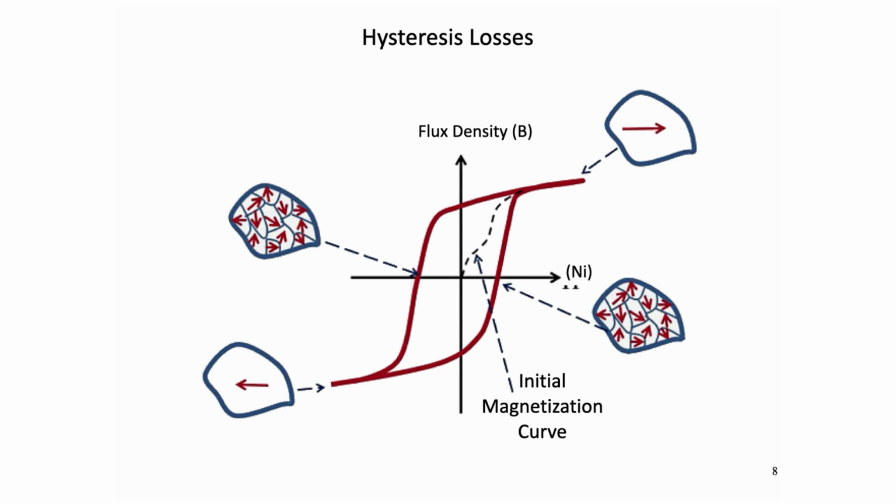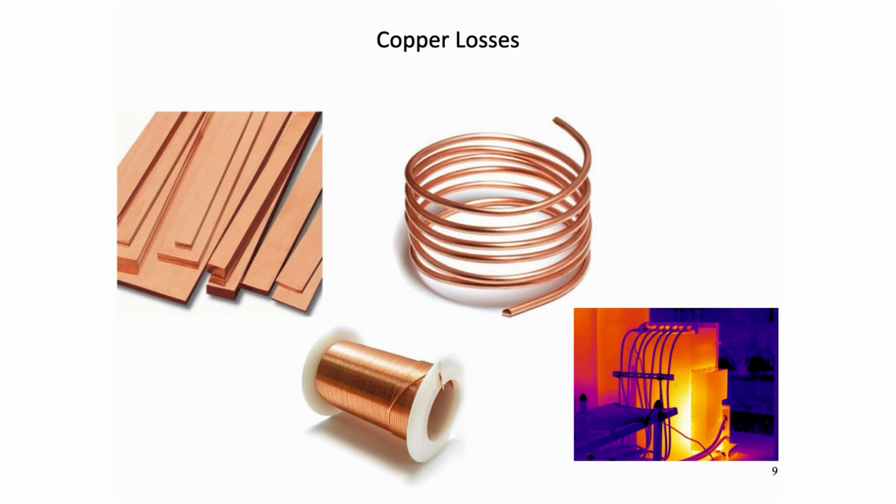Also, transformers are designed to operate at a particular supply frequency. Lowering the frequency of the supply will result in increased hysteresis or higher temperature in the iron core. So reducing the supply frequency, say from 60 Hz to 50 Hz, will raise the amount of hysteresis present, decreasing the VA capacity of the transformer.